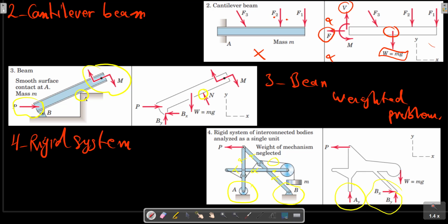We use the free body diagram in writing the equilibrium equations, which are discussed in the next article. When these equations are solved, some of the calculated force magnitudes may be 0. This would indicate that the assumed force does not exist.